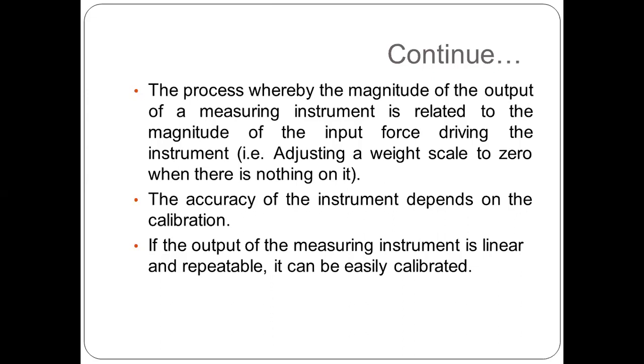For example, suppose you have to measure 5 kg of weight, then you can simply press zero and remove everything from that particular weighing machine. The weighing machine should be free, with air only. Then press zero, which means it is set to zero. Then we measure the thing. So whatever we are going to measure is calibrated from zero.